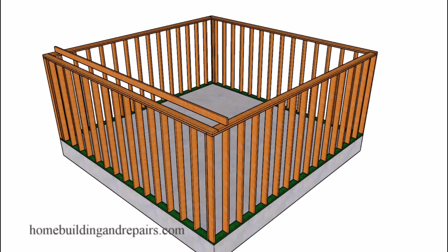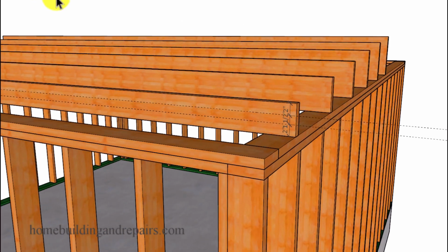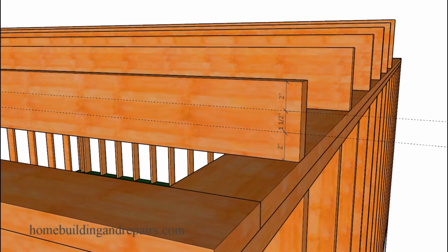Here is a video that will be helpful for anyone who has a floor with 2x6 or 2x8 floor joists and would like to drill a hole through that, or might be figuring out whether or not your joists need to be replaced because someone drilled a hole in the wrong spot or too large of a hole. And according to the 2021 IPC, or International Plumbing Code, in the structural safety section, and I will put the building code reference number in the video description box, you cannot drill any section of your hole in the upper or lower 2 inches of your floor joist.